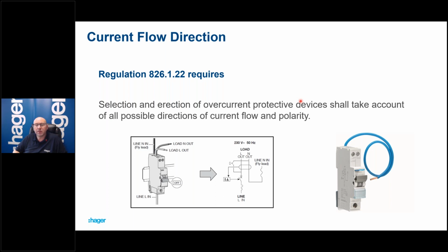And the problem is, if you put power in the opposite direction, you can damage the RCD element of the device, and the device will sit there. It will still work on overcurrent, but it may not work if there's a residual current problem, and that could be a problem if you're using the device for additional protection, you know, if the cable's in the wall, etc.